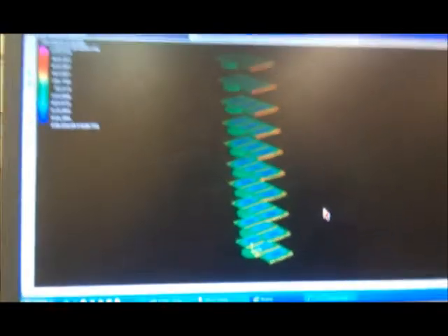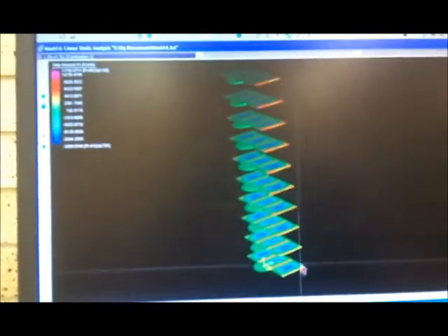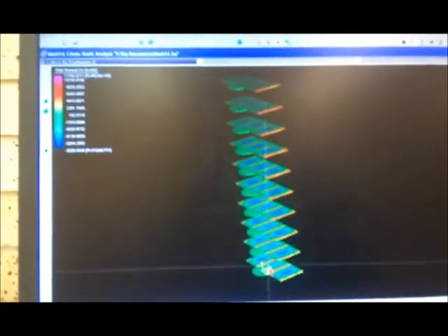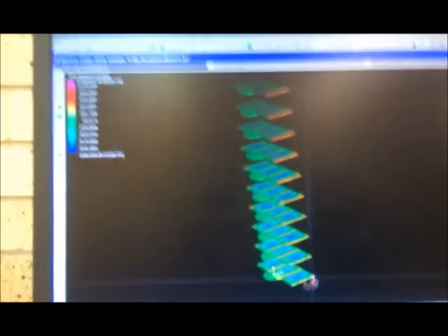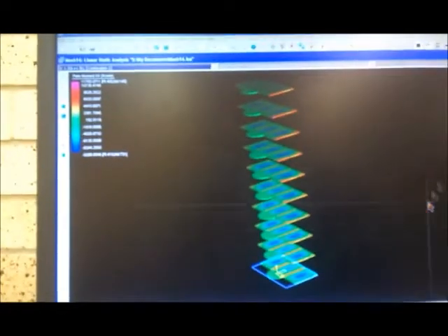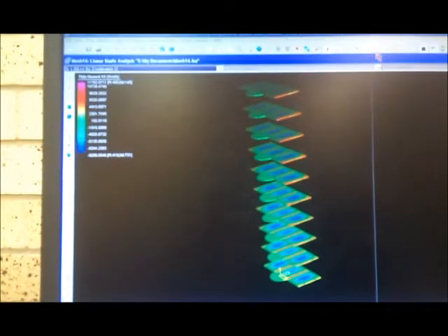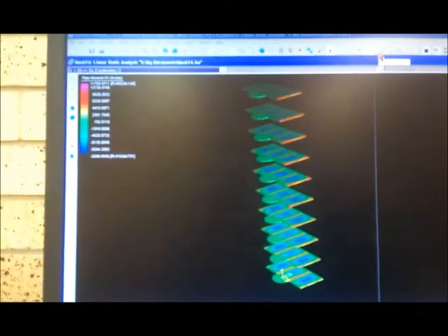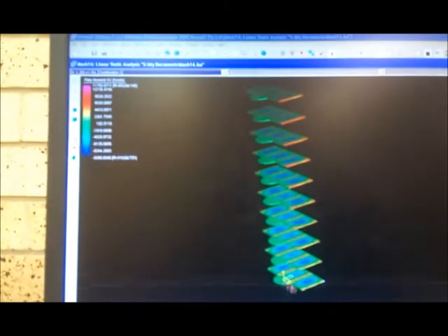Now, it's also expected that they will all be more or less similar. So I'll just look at one of them. I just want to look at one floor. So I'll do the same thing again. Select by region. It didn't select the plates because plates are not active from here, isn't it? I'll make plates active and select by region.